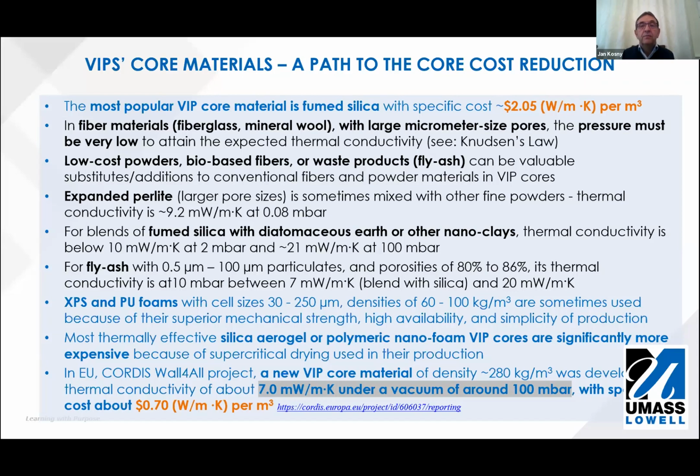Regarding the cost, the specific cost of fumed silica is about $2, a little bit over $2. Recently in Europe, several European projects were focused on development of lower cost, and actually they reached about 70 cents. So cost was reduced 3 times. Not necessarily with the same quality of the vacuum core material as fumed silica.